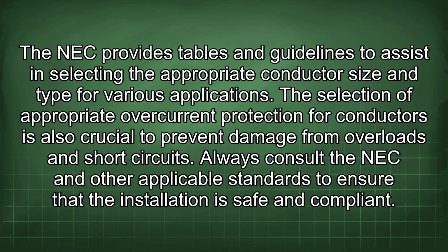The NEC provides tables and guidelines to assist in selecting the appropriate conductor size and type for various applications. The selection of appropriate overcurrent protection for conductors is also crucial to prevent damage from overloads and short circuits. Always consult the NEC and other applicable standards to ensure that the installation is safe and compliant.